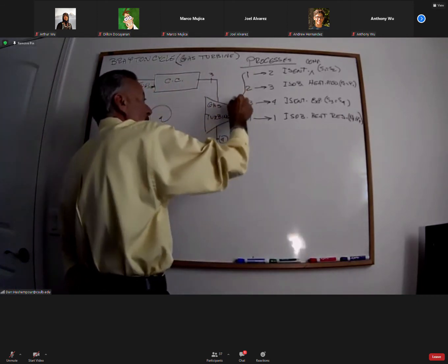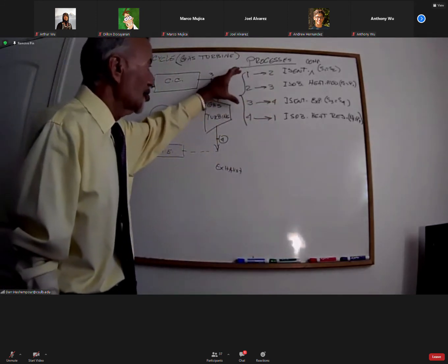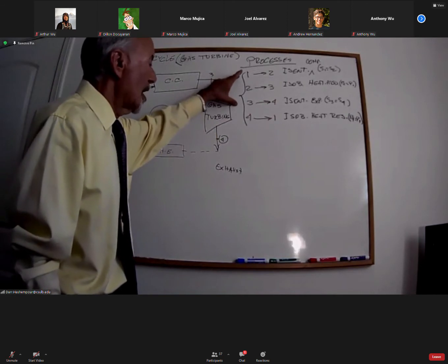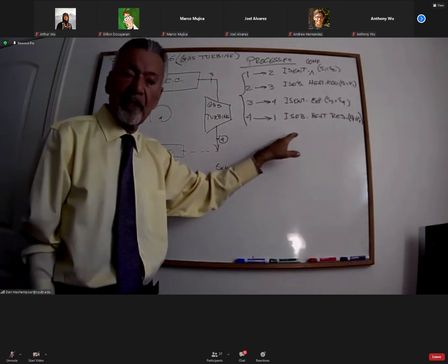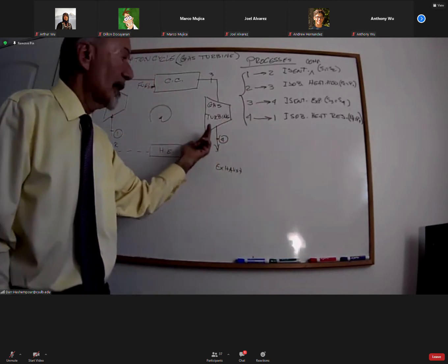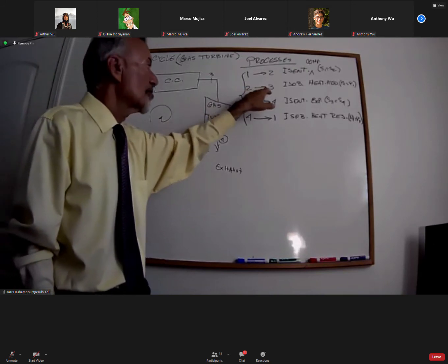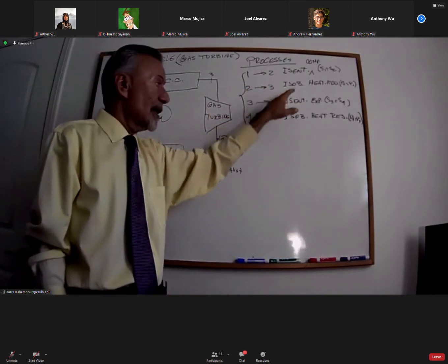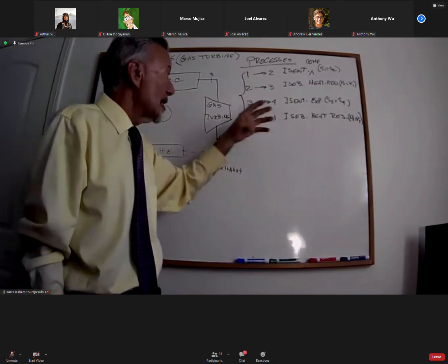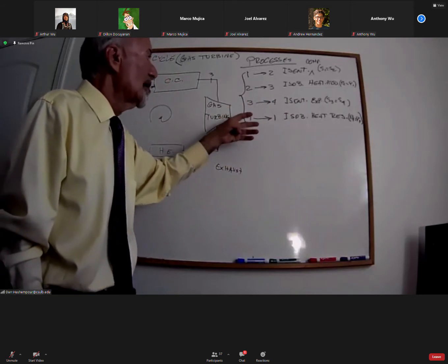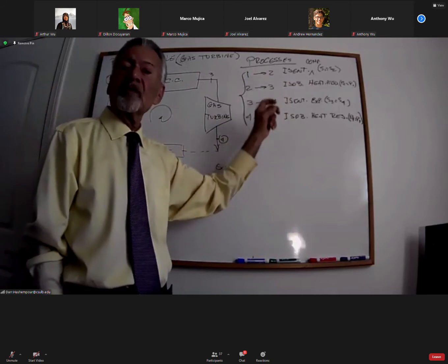As you can see, in the Otto cycle, these two processes were the same. The Otto cycle put 2 to 3 and 4 to 1 at constant volume. Diesel came along, changed this one only to constant pressure, and kept that one at constant volume. Now, the Brayton cycle is saying we have 4 processes, 2 of them isentropic, 2 of them isobaric.